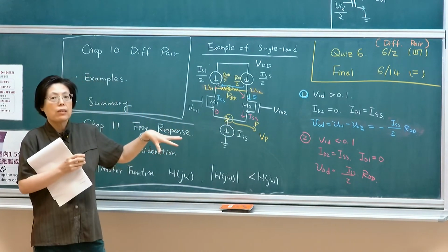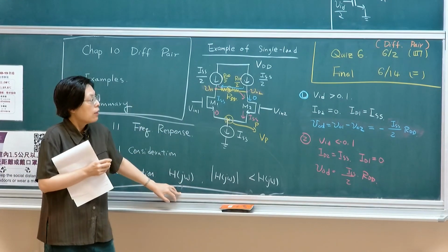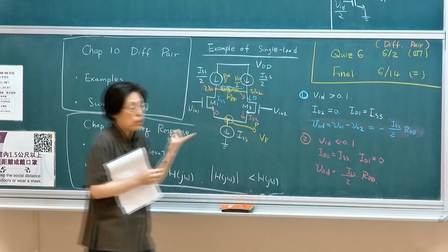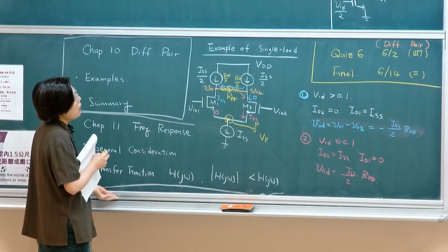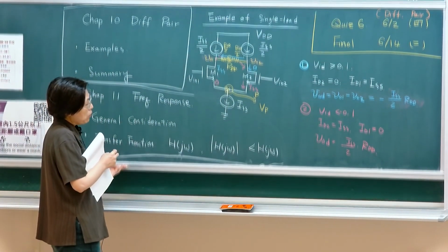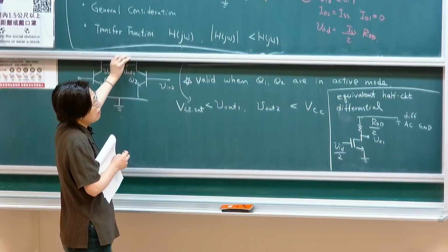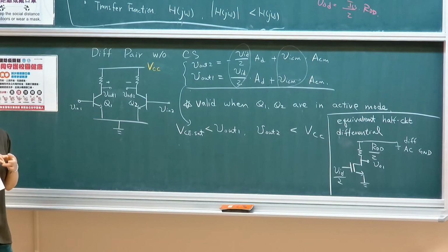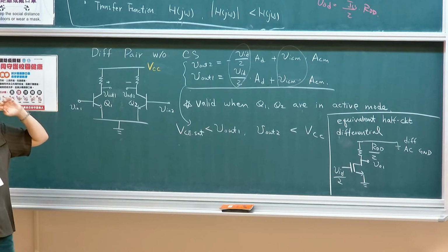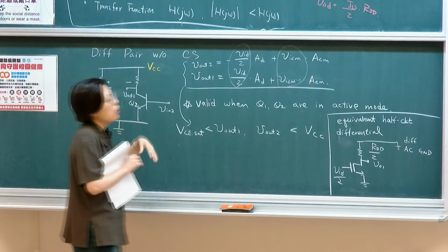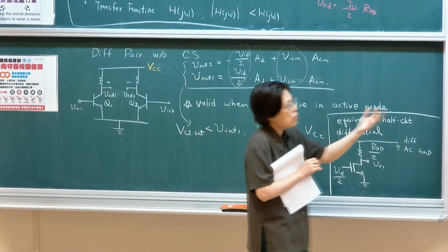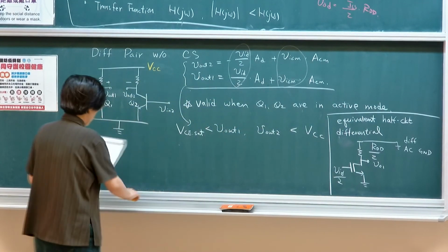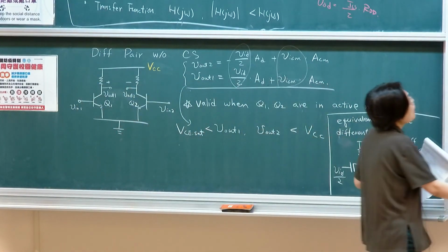So the purpose of having this type of structure is that there's no mismatch. Because I only have a single resistor, you can actually have a much better matched structure. However, you still will experience mismatch from transistors, but there will be no mismatch on resistors, if you are trying to reduce the elements that inject mismatch. Okay? So finally, let me